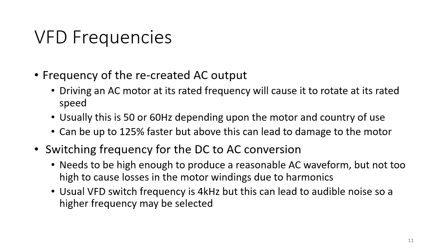Typically that's 4 kilohertz. But that can lead to audible noise, which can be annoying in some applications, particularly in consumer type applications, maybe where you're driving a lift and you've got a lift hoist motor. If there's a 4 kilohertz noise, that's a high frequency noise which people can hear, and that could be very irritating. So sometimes you might want a higher frequency so that you still get your good AC waveform, but you don't get that 4 kilohertz. But normally 4 kilohertz is about the optimum, because any higher than that and you do get losses in the motor windings due to harmonics.